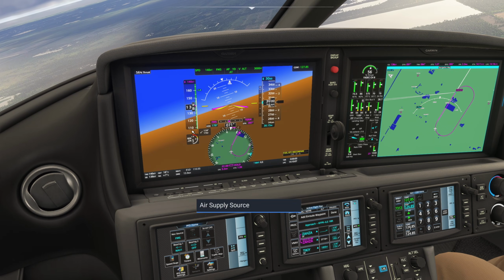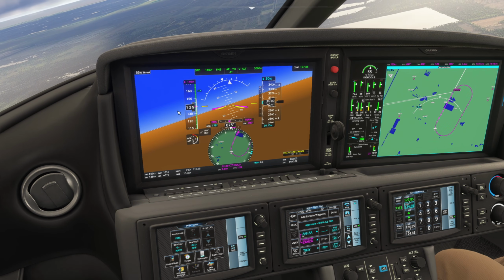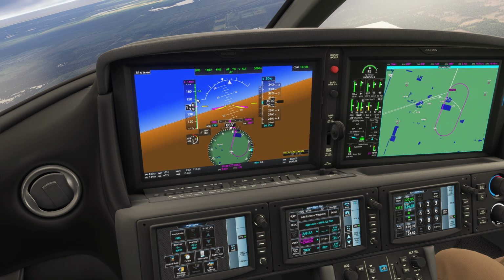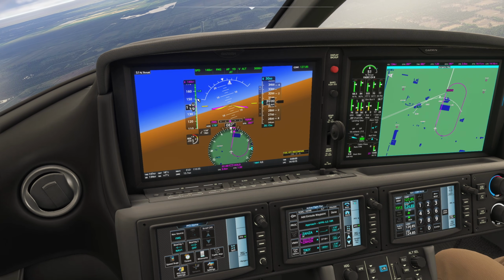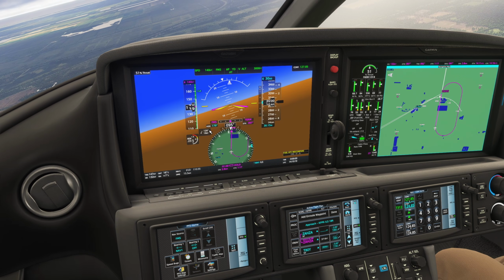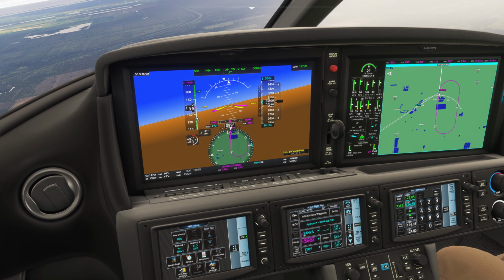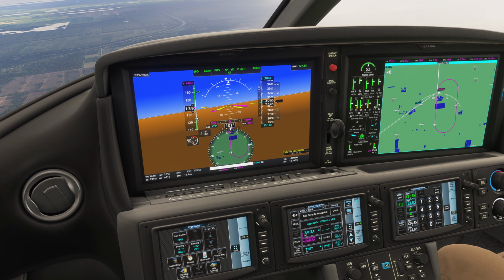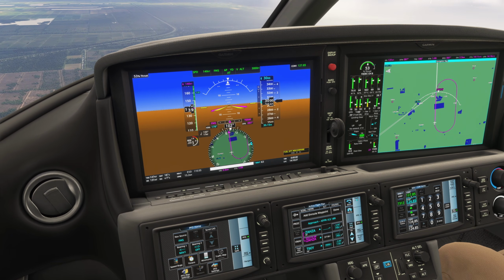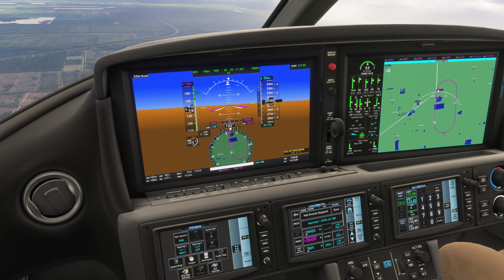Our full flap speed is 150 knots. I'm going to write these all in the description for you. So we can't use full flaps above that, which is also represented by that white line. That's VFE speed, velocity flaps extend speed. Our stage 1 flap can be extended at 190 knots.